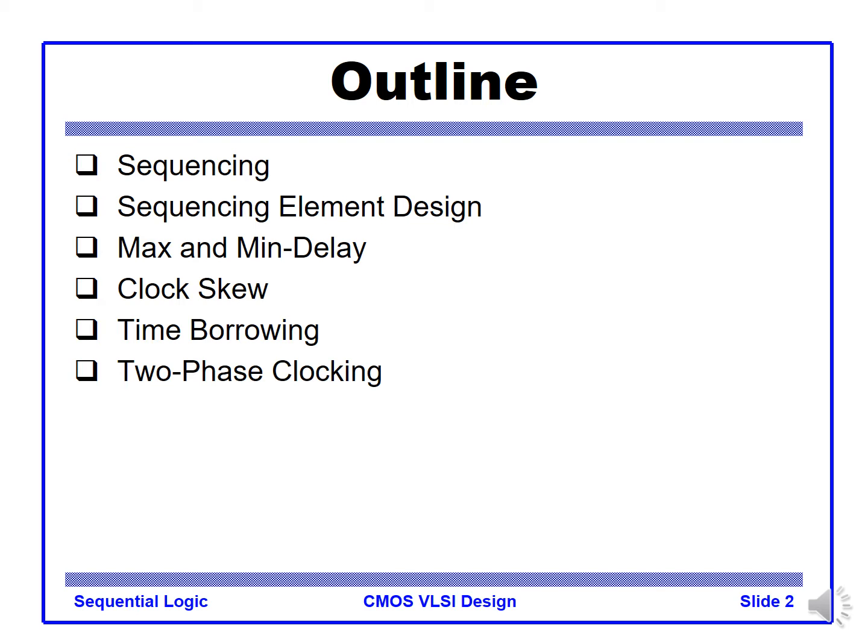And we will also cover the maximum and minimum delay, because the sequential elements operate based on the clock, the periodic signal. In that case, you have the maximum operating speed limited by the clock frequency, and then it has the period, one clock period you have to complete.